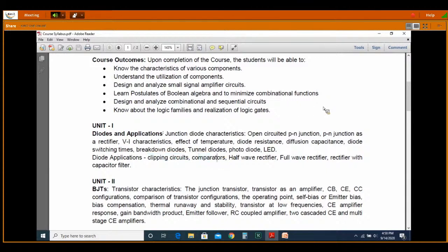Now we are taking the ramp signal as the input, and with respect to the ramp signal, we are comparing the input signal with the reference signal. If you are getting a constant output, that indicates the input is smaller than the reference signal. If the output is following the input, that indicates the input signal is greater than the reference signal. That comparison is all that is done by the comparator.